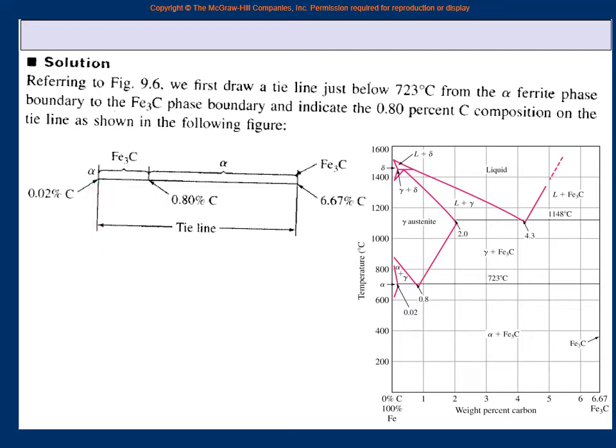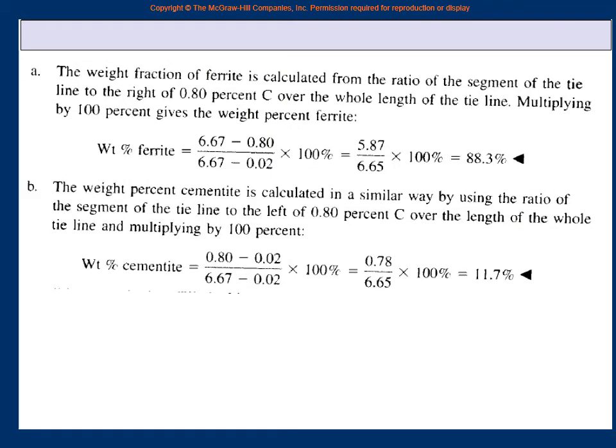The iron carbide diagram is just that. It is another example of the last chapter. In the last chapter, you have already learned everything that you wanted to learn to understand this. It is just that the new example is a steel, which is iron and carbon. You are applying it, but otherwise you know it. So you have noted down left side 0.02%, center the original W0 0.8%, and right side 6.67%. So just apply it and calculate it.